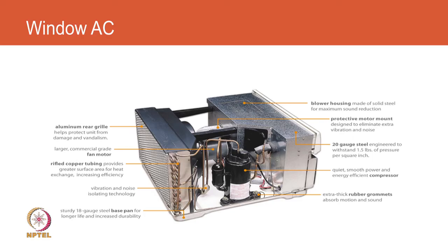Then we have the heat exchangers. What you see in the condenser, there is a similar heat exchanger also in the evaporator, but it is covered by the housing. When we design an air cooled heat exchanger, we need to look at several parameters. One of them is fin density, how many fins per inch, and that is one of the commonly used parameters because it defines manufacturing and tolerances at the component supplier end.